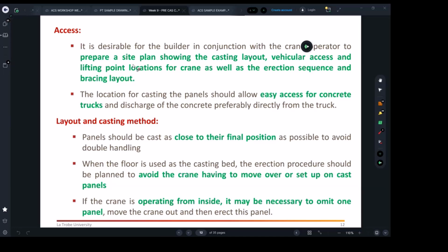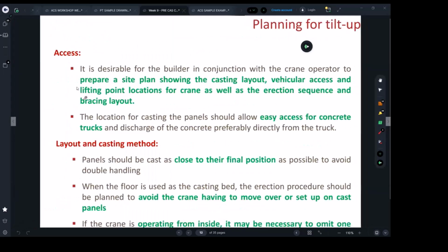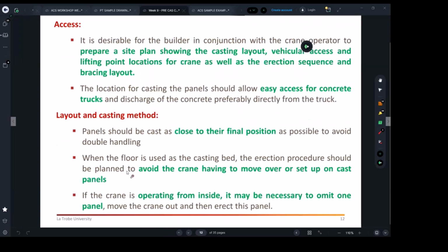That all needs to be timed and thought about to prevent needing extra time to build such panels. And then you're going to compromise the point of using precast. Precast panels, definitely, are well known for saving construction time. And if things were not planned correctly, in terms of what we covered here, or in terms of the access, that will compromise the timing advantage.